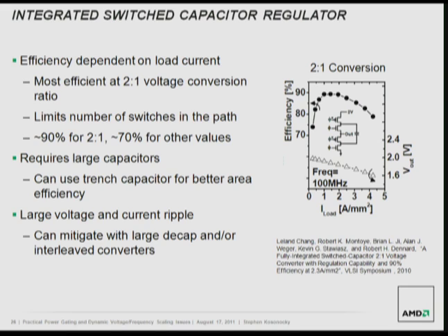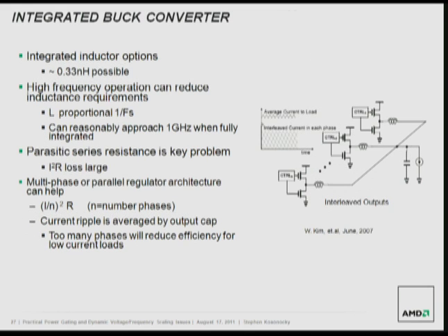The next one is there's also a large voltage and current ripple associated with that. And that you can really mitigate with something like a very large capacitor outside, again, to help smooth that out.